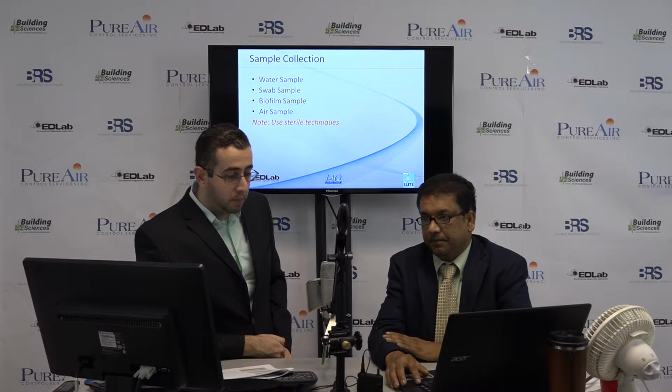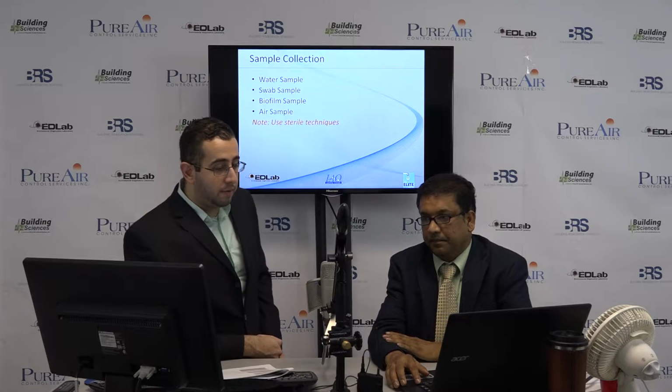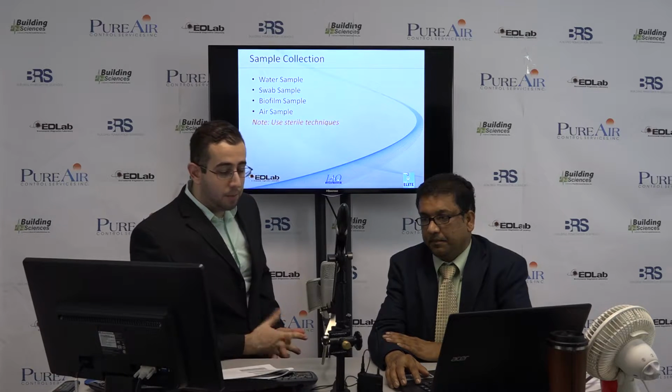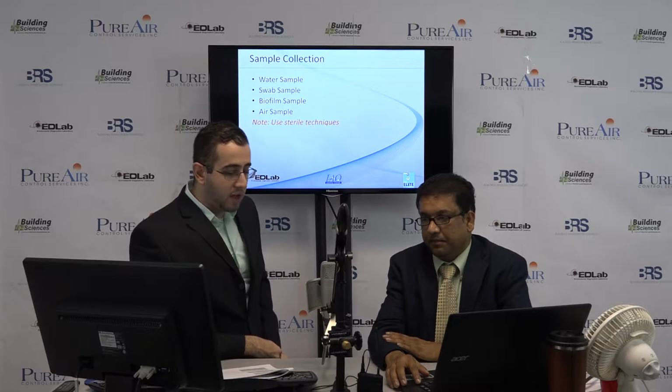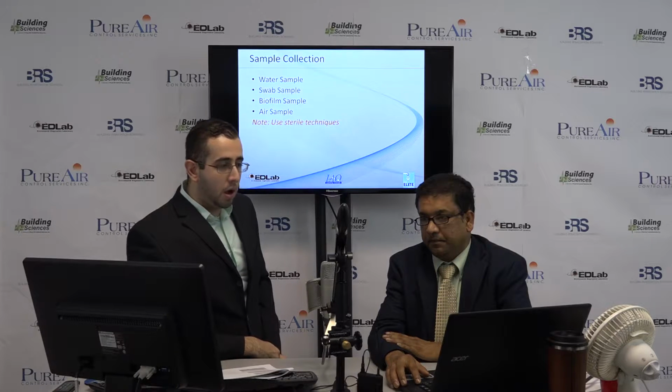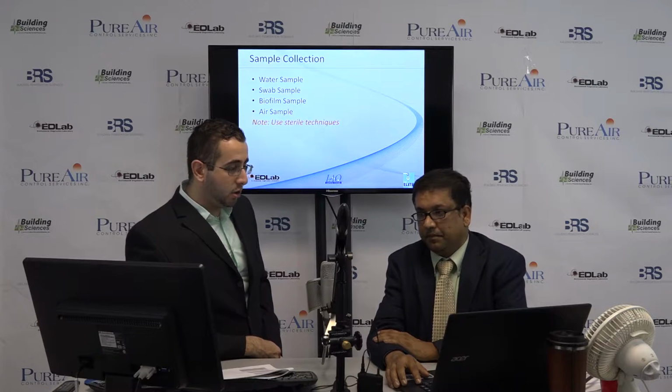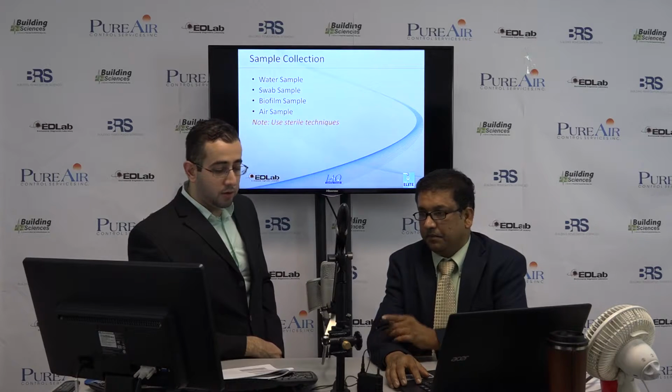A biofilm sample is something along those lines, where if a biofilm is detected or visible, one can collect it a number of ways, whether with a gauze, a swab, or some other method that can be used to collect Legionella as a whole. And finally, an air sample can be taken to detect Legionella, as I was stating earlier, because typically with Legionella it is aerosolized as a mode of transmission.